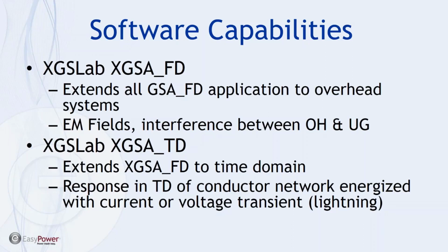So you gain a lot more capabilities with the above ground, and you start getting one step closer to modeling, or actually you're to the point now where you can model reality and really do some almost academic level studies and answer very specific questions on your grounding system when you have to worry about above ground facilities.